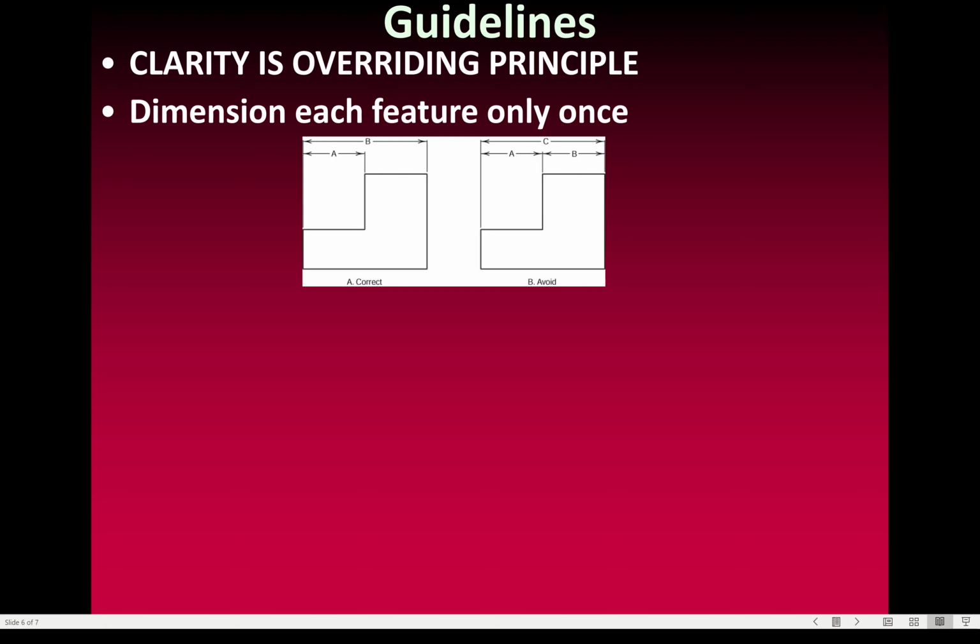You would only need two of these three. And again, which two you choose depends on the design. Sometimes you won't know, it depends on if you're designing or not. But a lot of times it might be important for the overall dimension to be 2 inches, so you'd want to put that in there rather than each aspect of it.